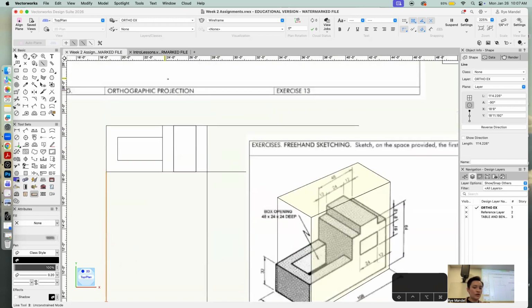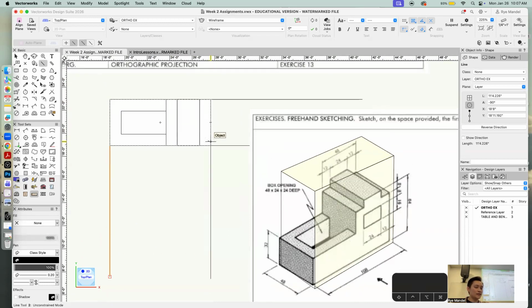You can also go north. That's also a perfectly valid way to do it. I happen to do this going south. But let's say this is your two lines that you made. You already know this dimension is going to be 108 inches wide. So you can take those measurements and snap it to these lines. It'll just hover and then it'll snap for you.